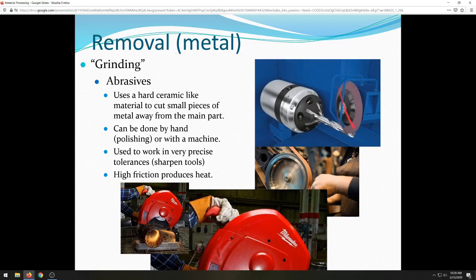So that's how we grind things like tools and drill bits. All these little bits have to be extremely precisely ground, so you put them in specialized machines that have specialized abrasives, and they just take really light cuts. But then we also have really raw, rough abrasive processes. Down here you're looking at a chop saw. We do the offhand grinder if you wanted to grind out a weld. Those are very imprecise processes. Again, very rough, very raw, not accurate at all.